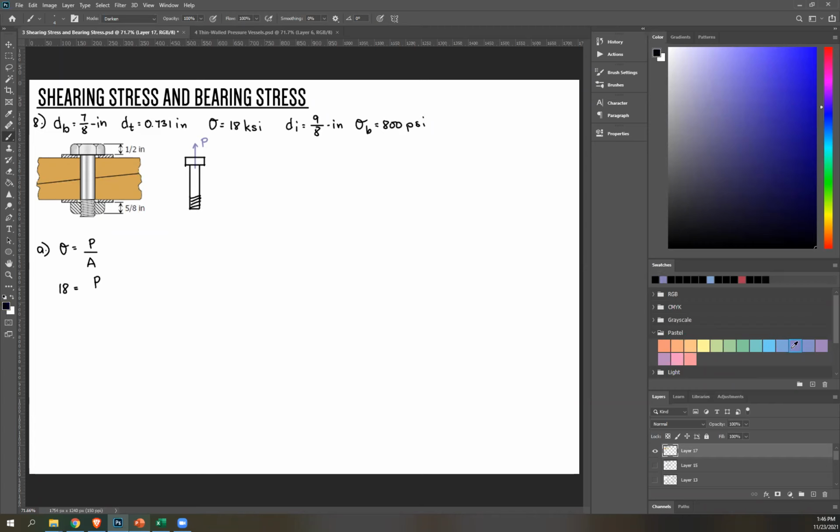And then that tensile force is being resisted by your shear force between the bolt and the head and the thread. So in short, there's a reaction force V here. So therefore, V equals P. So we just have to look for P, which is this.